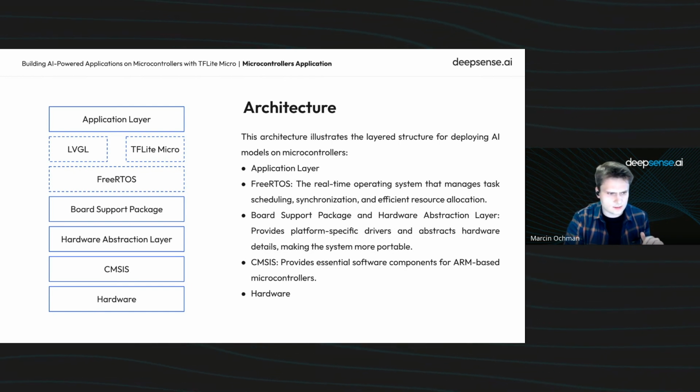Moving upward, FreeRTOS is the real-time operating system layer. This layer is responsible for task scheduling, resource allocation, and of course, synchronization between tasks. FreeRTOS ensures that real-time constraints are met while managing the limited resources of the microcontroller.